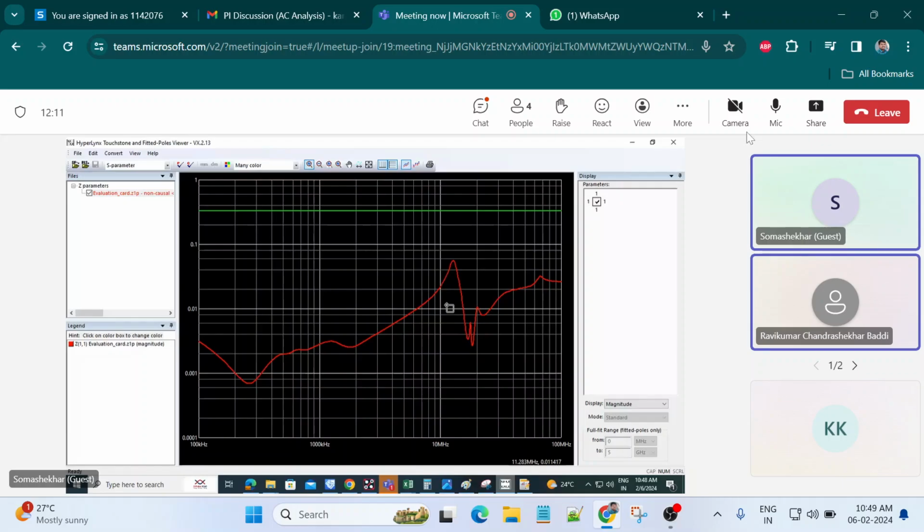The x-axis denotes frequency and the y-axis denotes what? Actually, is it farad or something else? And the red one is the PDN curve. Yeah, I can explain this curve. The up one is how you routed the shapes, how you put the shapes. The power goes from the VRM to the load, VRM to FPGA.